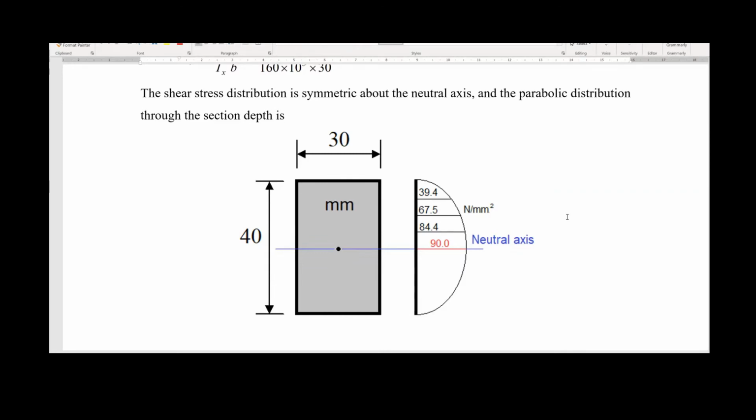And a way to communicate properly your knowledge and the result of your exercises is to show diagrams, because engineers understand a common language in the whole world, which is through the diagrams. So the bending moment diagram, the shear force diagram, the axial force diagrams, and the diagrams for stresses are extremely important. So in this figure in here, it's very clear that we did a series of calculations, and actually you can improve this one, including in here the distances of 5 millimeters to be 100% sure where the levels of these different values of stresses are.